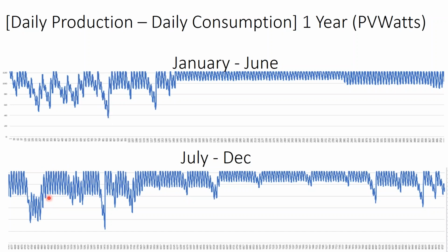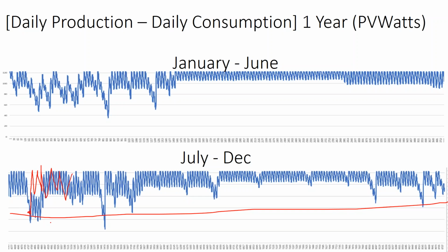Now, in reality, this battery is going to be operating not in its float and not really in its absorb phase, but it's getting further down into the bulk phase. So in reality, what's going to happen on this day is we're going to limit the battery bank to like 50% instead of 65. And as soon as it hits this mark, we're going to turn the generator on and get it back up to the top. This became a metric that I found very useful in comparing different battery bank chemistries, because the client told me he didn't want to have to rely on his generator. And I can tell him, well, you don't need the generator, but we're still going to use it to help the batteries out.